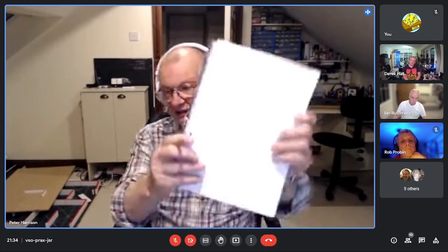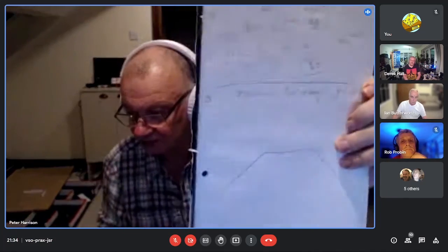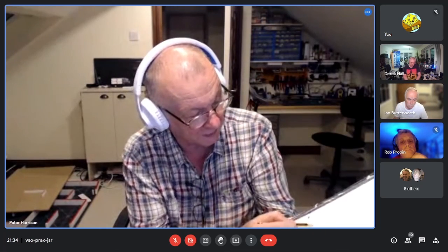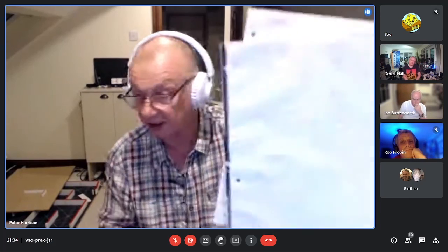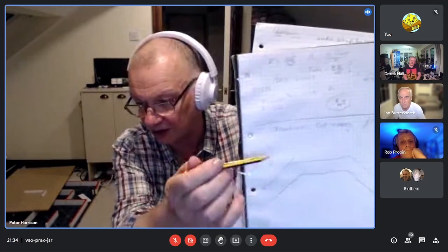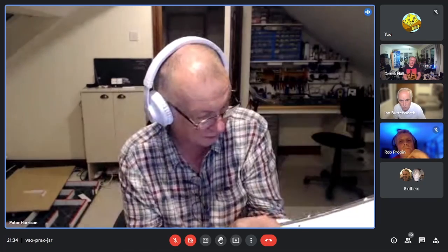So if that's the profile at the bottom, some strange angle, and remember with the feed forward, so that's 0, without acceleration, if the feed forward's the top one, it has no steps to it, it just starts at 0 and goes up to whatever the voltage is, and the controller previously was just kind of wiggling along at 0. If you leave out the acceleration feed forward, the controller output will look like that.